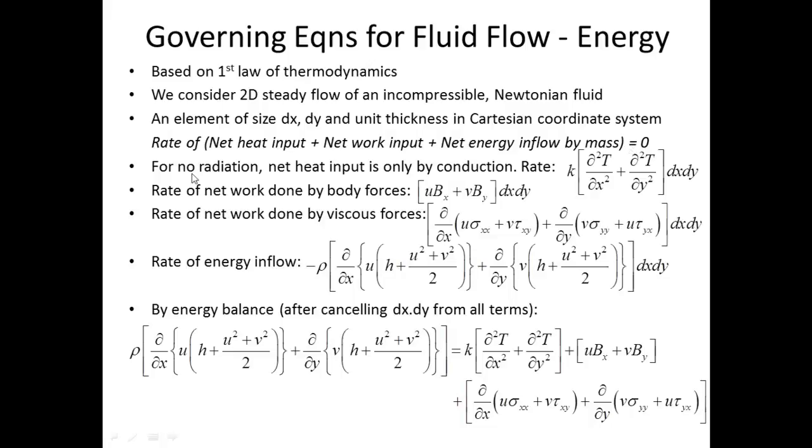If we neglect radiation, the net heat input into the element is by conduction, and that is given by the formula given here: k (∂²T/∂x² + ∂²T/∂y²) dx dy. Similarly, the net work done by the body forces is expressed in terms of those body forces and the corresponding velocity components. Again, the net work done by the viscous forces is also expressed in terms of the corresponding stress components and the velocities.